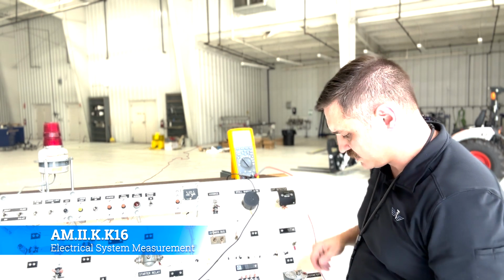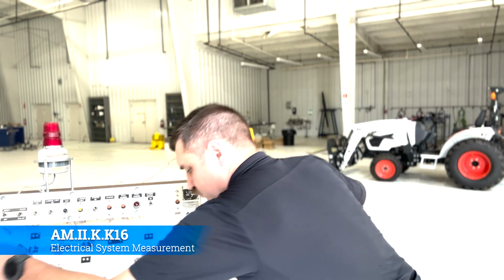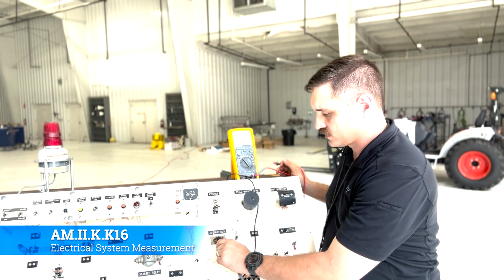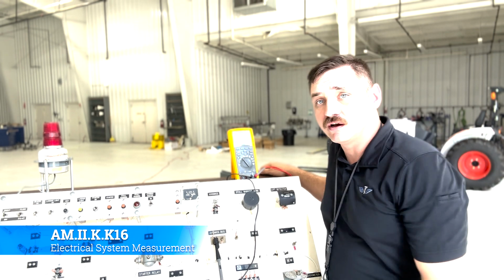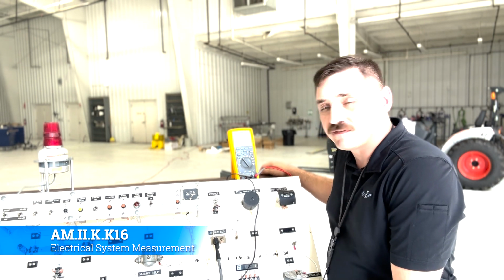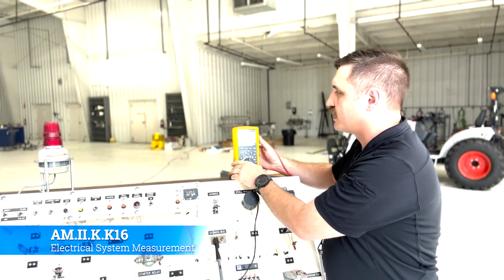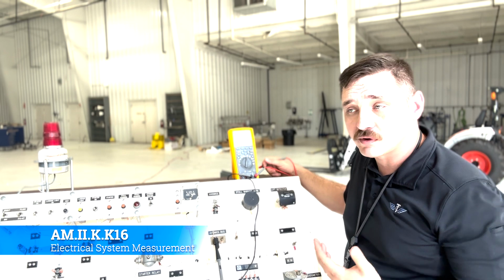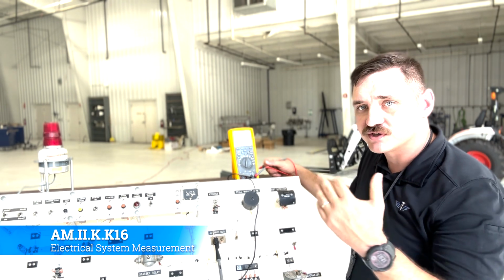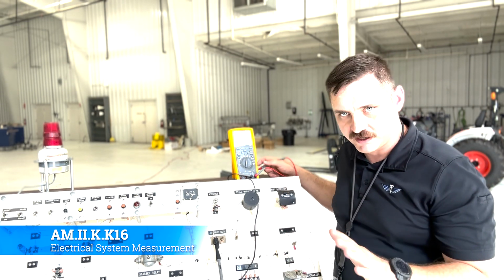So now let's start thinking through where else we could have lost something. If we know that there's no power going to the light bulb, and we want to find where that power should be, let's start doing some continuity checks and kind of mapping out where things should be. Now, this is normally where we would have a wiring diagram, and then we'd start to work our way back. You'll do that in class with the actual aircraft, but for the trainer, we don't have that, but it's easier to display this on video, so just bear with us.